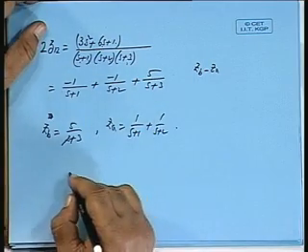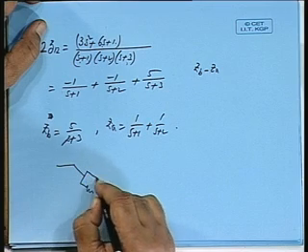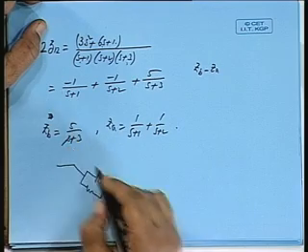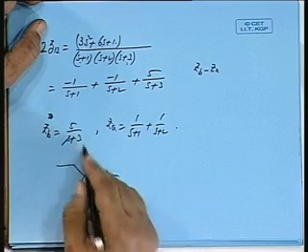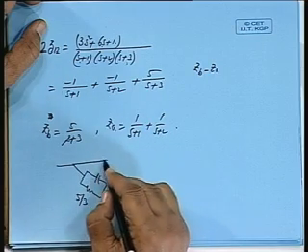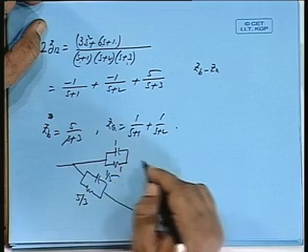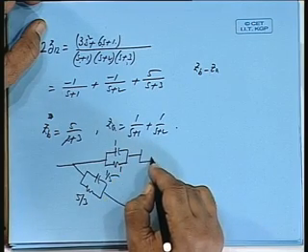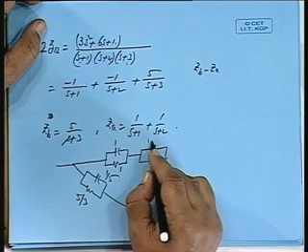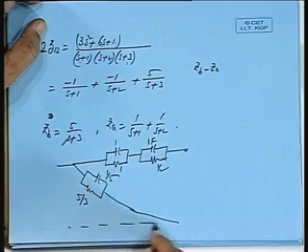5 by s plus 3 is 1/5 farad with 5 by 3 ohm resistance, and here 1 by s plus 1 is 1 farad with 1 ohm resistance, 1 by s plus 2 is 1 farad with half ohm resistance. So, this is ZA and ZB.